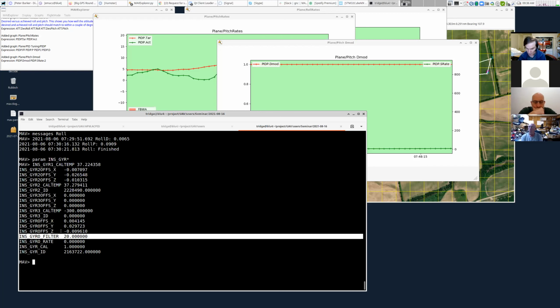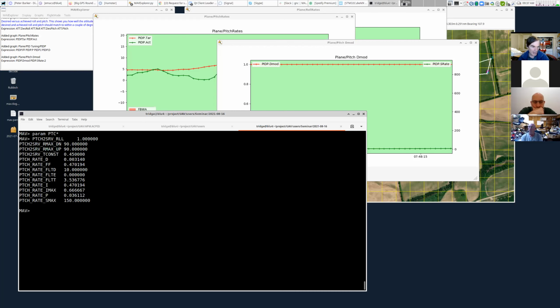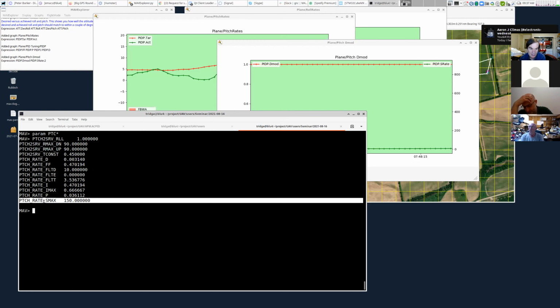But the first thing I would try is just start with the gains from the auto tune, but then push up that P and D gain a bit more. And I would probably start by doubling that D gain. These days, it's not a lot of risk pushing up the D and P a bit higher. You're not going to suddenly massively destabilize, because we have this slew rate max, which detects oscillation. So if you do push them up a bit too high and it starts to oscillate, it will oscillate a little bit, but it's not going to go totally out of control.